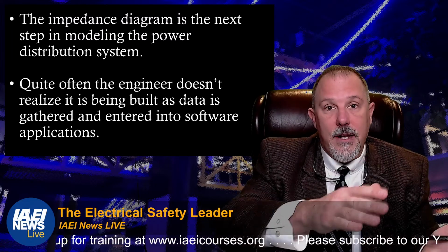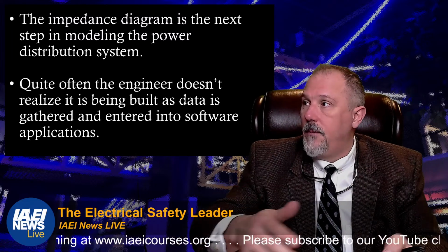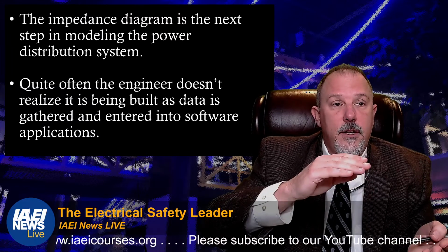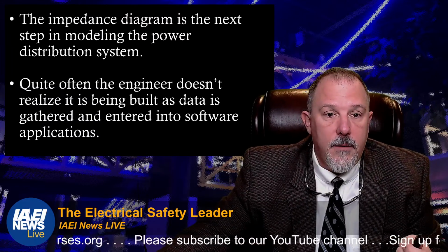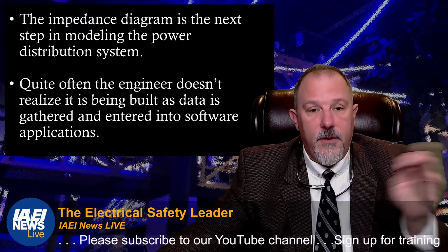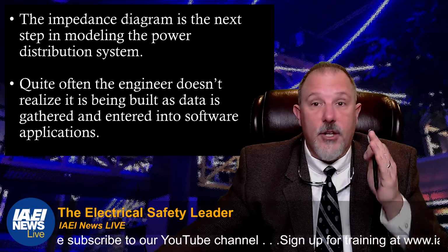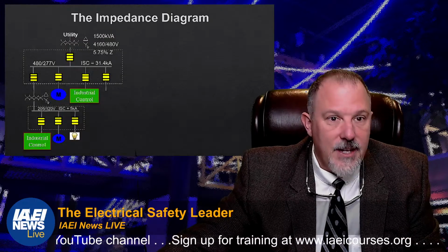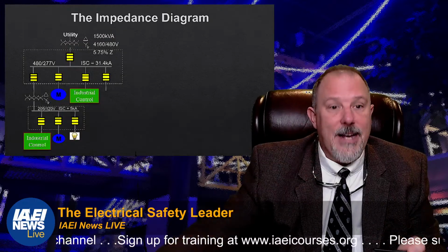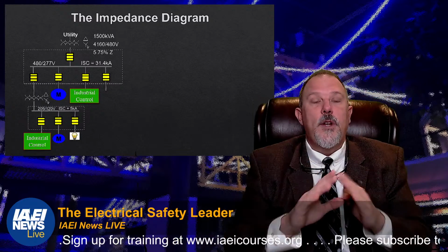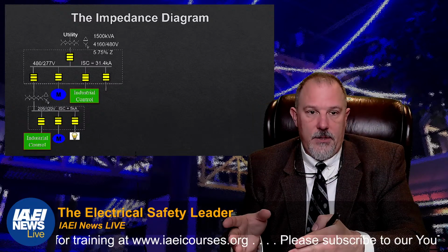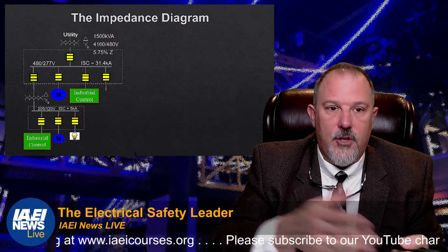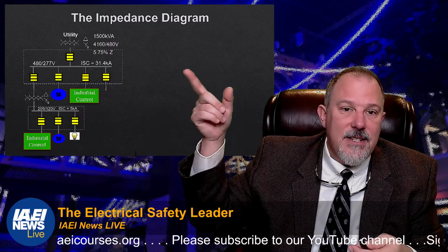So you take your one-line diagram and convert that over to impedances, because just like you said, for voltage drop and short circuit studies, right? So we'll take this one-line diagram and convert every one of these. Now, we don't convert fuses into an impedance. We don't convert circuit breakers into an impedance, or the bus inside of that panel board.